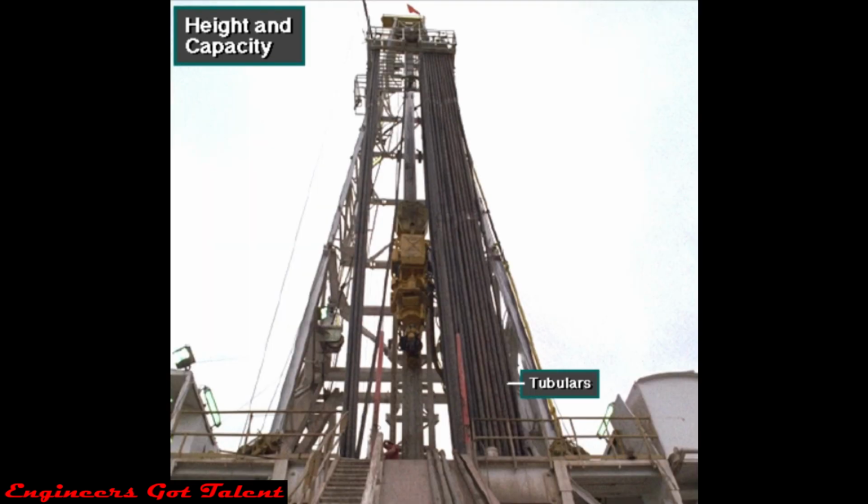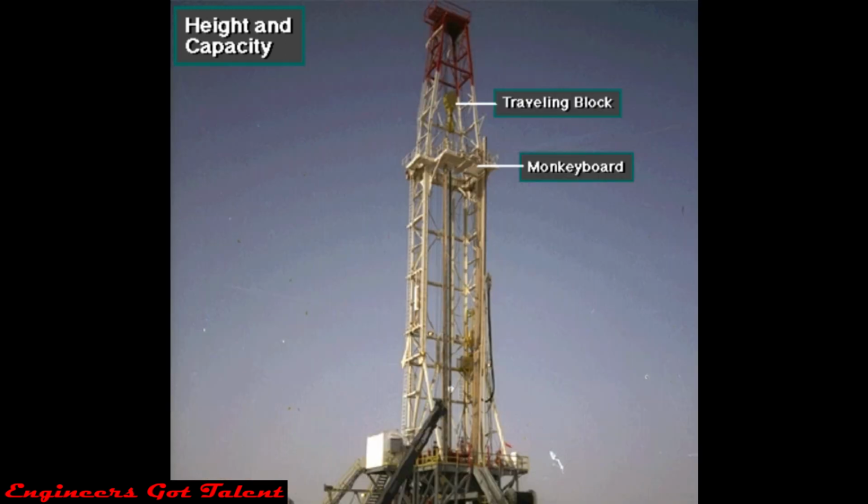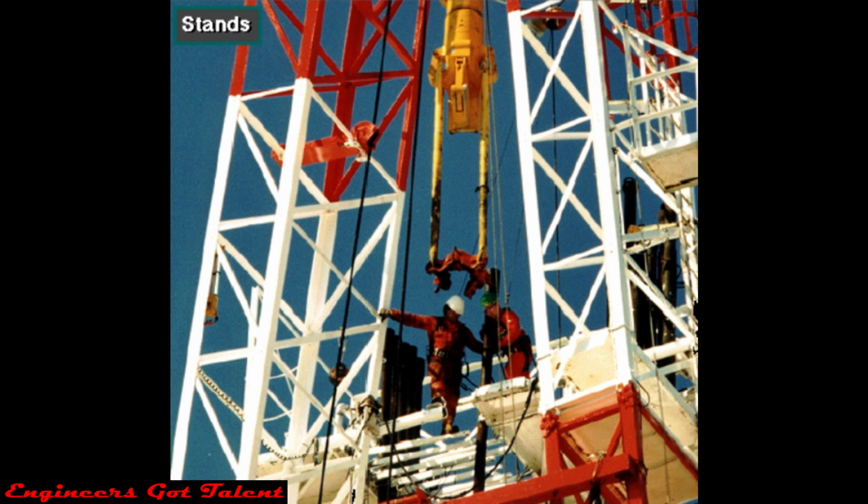A rig's mast must be tall enough to allow crew members to set back drill pipe, tubing, and other tubulars they pull out of the hole during a trip out. It also has to be tall enough to allow the driller to raise the traveling block above the height of the derrickman's monkeyboard. With the traveling block high in the mast and the elevator at the derrickman's position on the monkeyboard, the derrickman sets back drill string elements or stands.